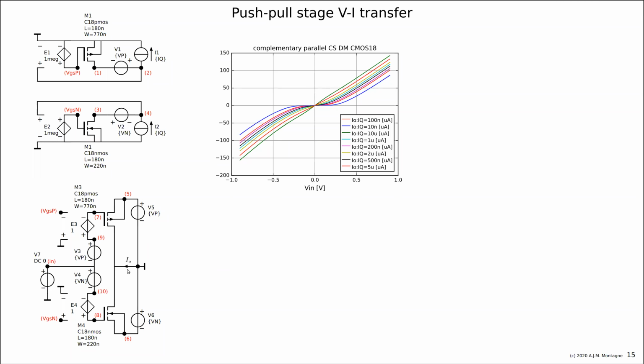Now, I unfortunately placed this arrow of IO from the ground to the drains, which means that source and sink and push and pull is a little bit messy. But the upper device, the P device, is sourcing, is delivering a positive current to the load. Here, a negative current, of course. And the other device, the N device, is sinking. It is taking a current from the load. You could say it in this way. So we have a source device and a sink device.